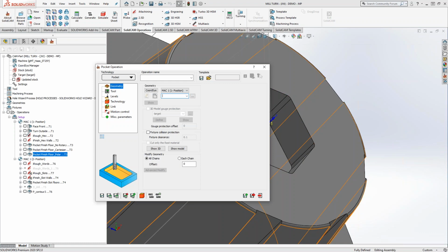Yeah, I was thinking it was a slot through there, so you didn't want to have an interrupted cut going through there. Well, to me, it's always the order of operations as well, because a lot of the times we have all these interfering features that one of them has to be done first. So it's either an interrupted cut right now, or it will be an interrupted cut once that slot is cut first, and then the pocket. So it's a matter of, probably need to see the actual part to understand what order things are being done in. But the geometry you have on screen can always help you.